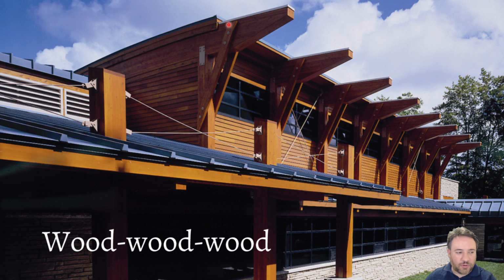The other thing that you will notice here that I want to point out while I have this picture up is this flashing. You see this steel flashing on top, or it might be aluminum flashing. It has a little lip on the edge that's very difficult to see. The point of this is, when water falls on top of this, to shed the water off. Especially important on this front face, because this is the end grain of the member.